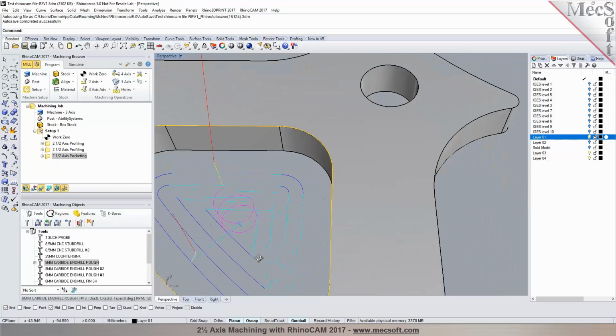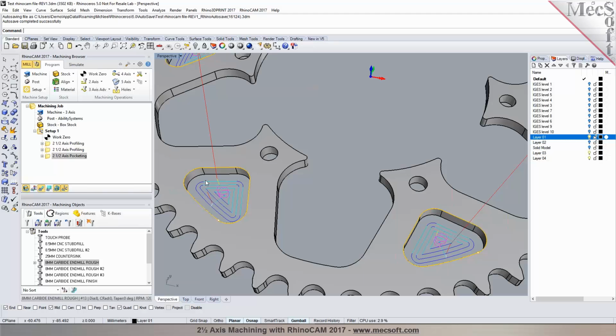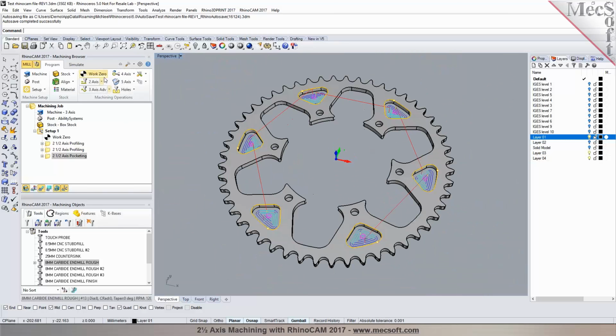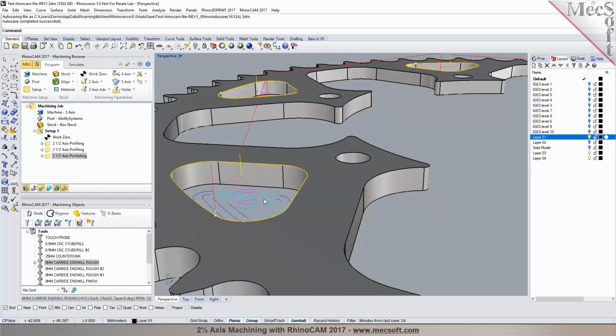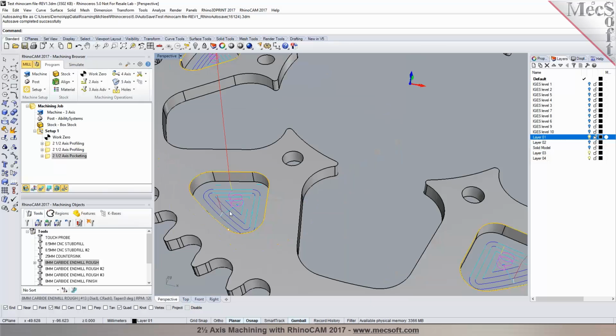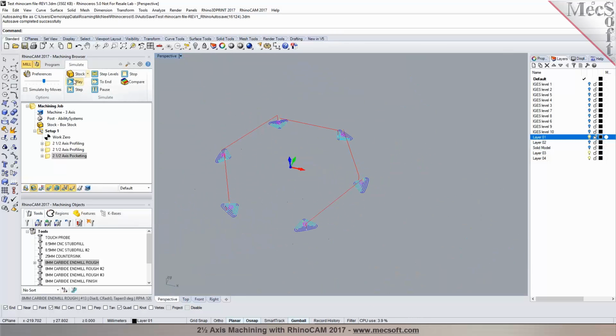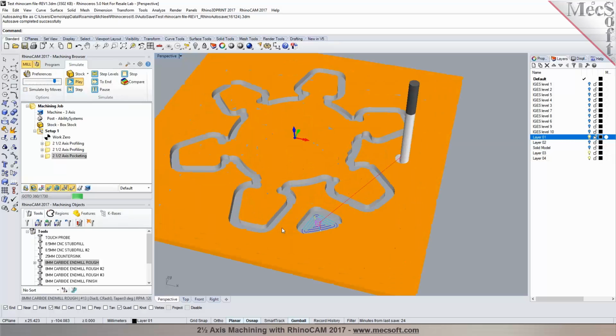So this is the offset cut pattern where it creates a uniform offset of the curve geometry. Right. And it's got a spiral leading. Yeah, it's doing a helical ramp, a path ramp right there. Now I'm going to go to the Simulate tab and select Play to run the verification. And we are still leaving the 0.2 millimeter stock from the sides of the pocket.